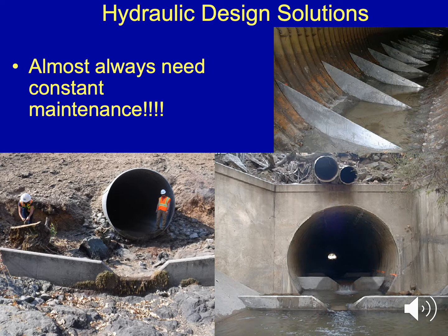Hydraulic solutions, there's a large suite of them. Often they are baffles within a culvert, concrete, steel. They tend to look nice and shiny right after installation. A few high bed load transport events later, they don't look like this anymore. They often also contain some level of trying to backwater the outlet to get fish up and in.